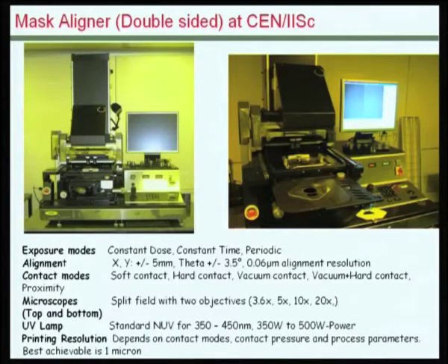So, we intentionally create alignment marks in every processing layer, and these are required to be carried through till the end of the processing, so that proper alignment would be possible. In this particular case, what you see is a double sided aligner, in which case you can see it from two directions, from the top and bottom, and that is also important in the context of building microsystems.